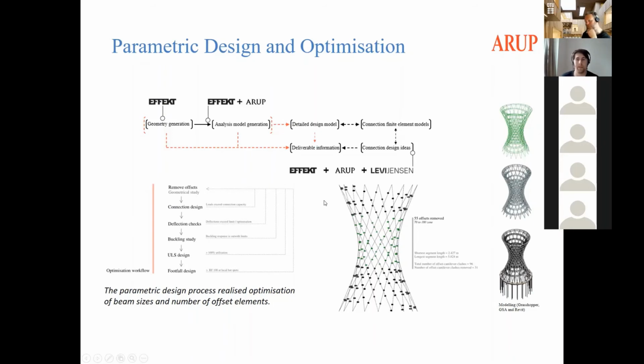Furthermore, we were seeing that at locations we had an issue with the cantilevers welded to the ramp ring. So that connection was clashing with the offset connection. And by having everything in code, we could quite quickly look at this clash and make sure that it didn't happen, basically by moving the cantilevers.